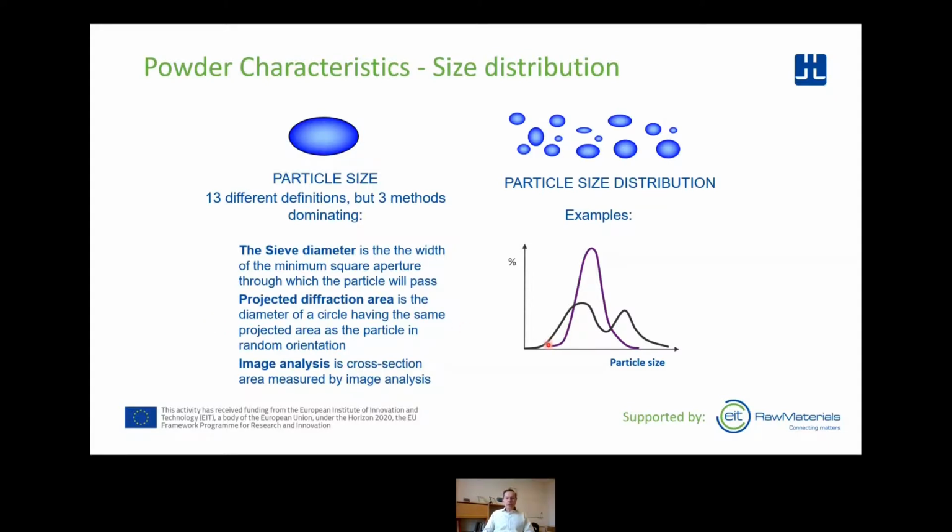For an atomized iron powder, for example, the size distribution is typically a normally distributed Gauss curve shape like this. But in the mixes we typically sell, where we have admixed graphite, perhaps copper powder, perhaps also a lubricant, of course these added powders have a different size distribution than the base powder, the iron powder.